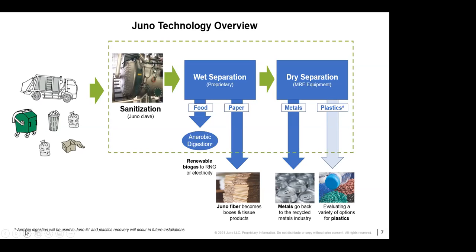And then, so once we take the fiber material, that obviously goes to our OCC pulpers, as I mentioned, and then we're producing, at this facility, boxes on the back end. And then you have the residues that are coming out, and that's where we're separating out the metals. And we're collecting all the metals off of that, and that's just through simple technology. And we're looking at, okay, now that we have these other residues, there's a tremendous amount of plastic in there. So our next step really is to capture that plastic and determine what can we sort out, what has a high commodity value that we can really reuse and resell, and what is mixed plastics and what can we do with that mixed plastics.